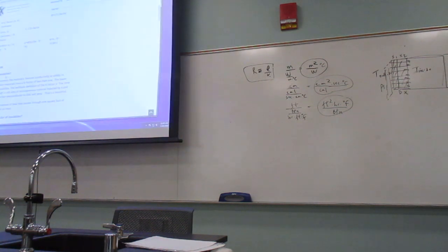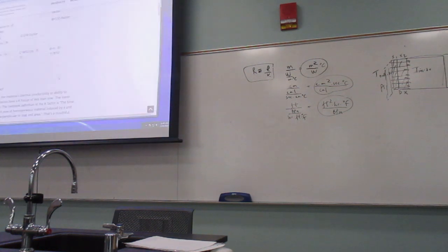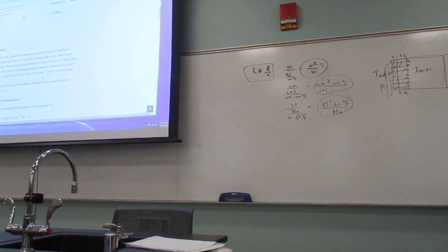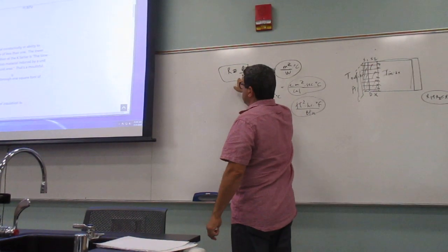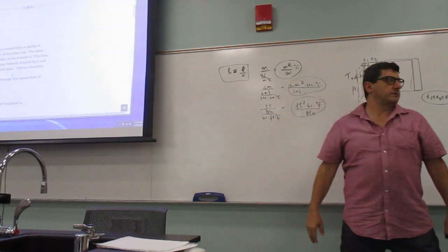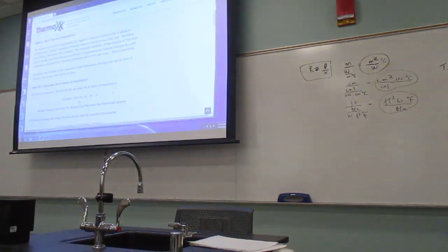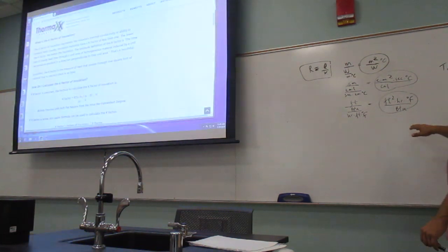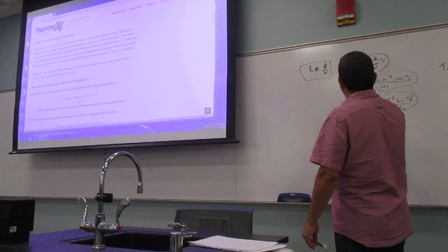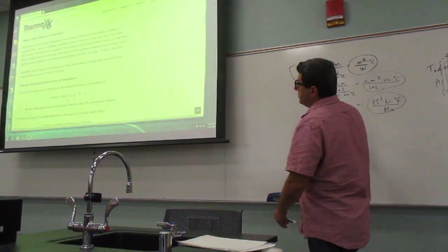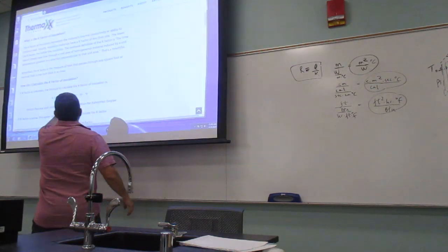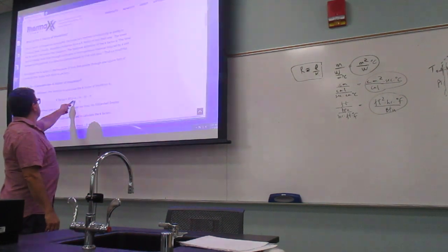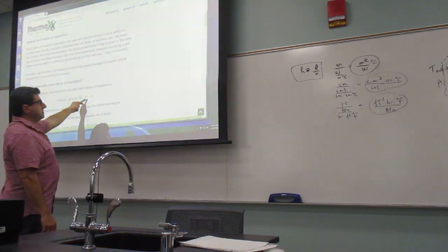You see, the K factor of insulation represents the material's thermal conductivity, or the ability to conduct heat. You see that? So the K factor is just the top, just this portion. So what's the K factor? BTU inches per hour per feet squared. What was my K? BTU per hour per feet per Fahrenheit. They're saying BTU inches per hour per feet squared per Fahrenheit.